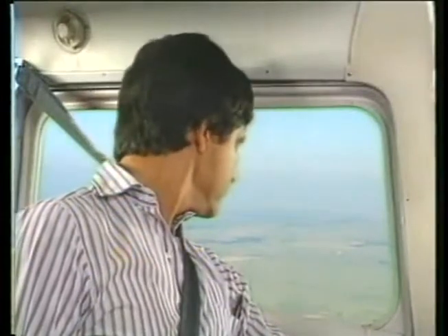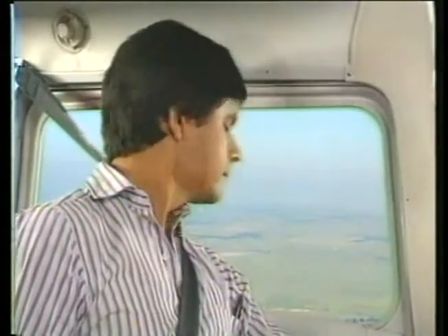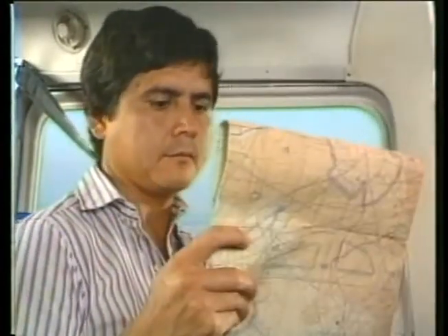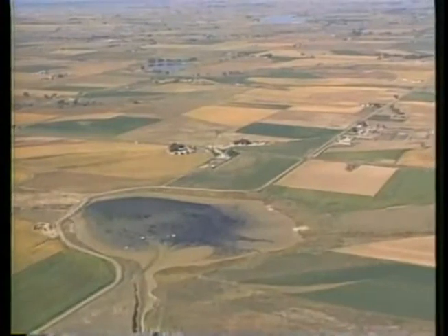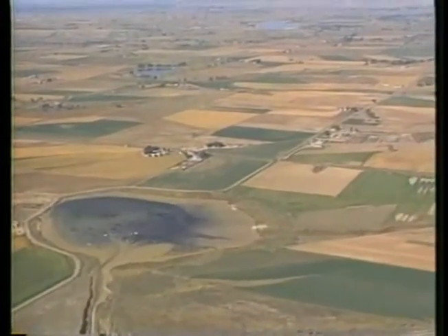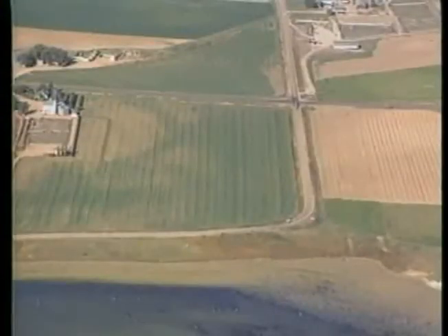The key to pilotage is selecting reference points along your route that are easy to identify from the air. Let's look at some examples. Lines that intersect or that form unusual angles are good checkpoints. Here, the jog in the road just before the intersection makes it easier to identify from the air.